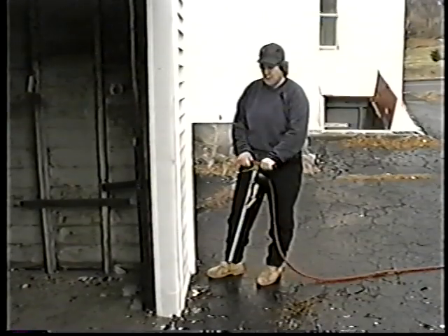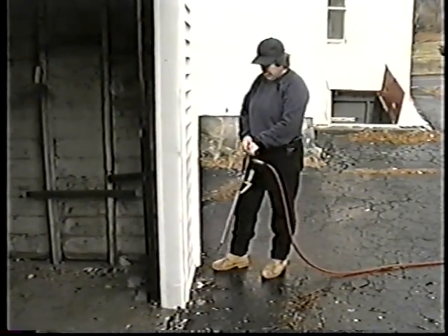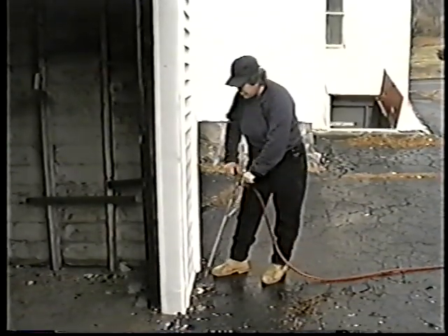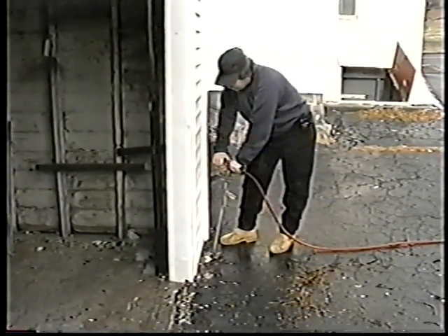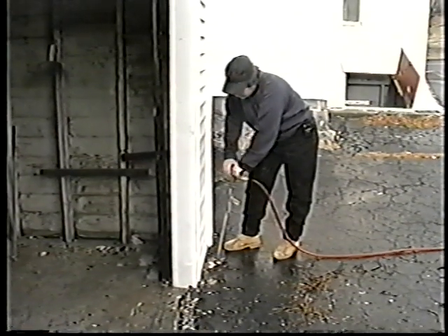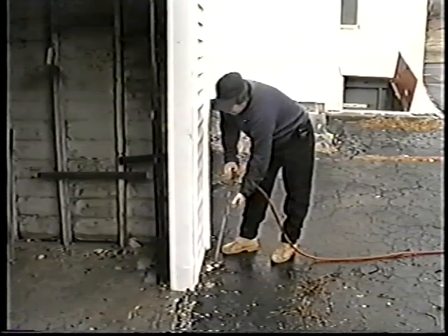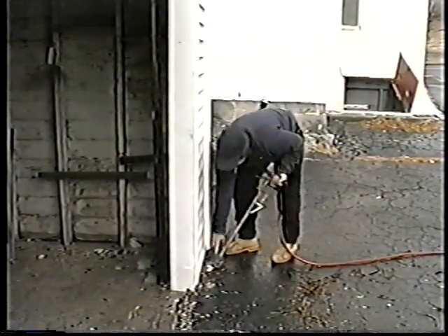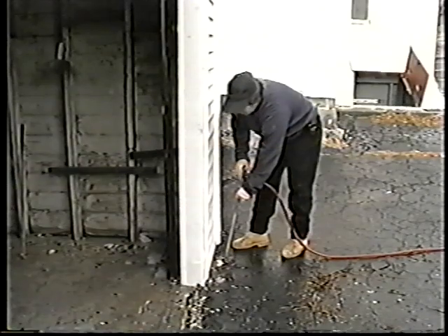And I'll get ready to pump some holes for you. We're going to pump these holes with the liquid, and this is called a sub-slab injector. What it does is it locks on these holes and it pumps the liquid. We just stick it in there, and we lock it, and then we pump. And as you can see, there's a little liquid coming up there, and that's normal. What this does is at 180 degrees, it actually shoots this liquid out to hit the whole area into the ground. And we have to pump these.